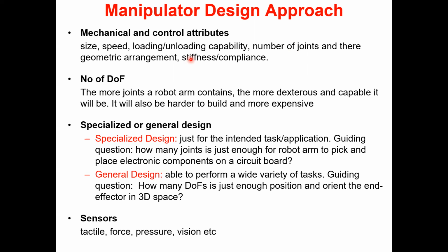One way to reduce the contact force is to deviate from the trajectory. Okay, you have a desired trajectory, and when you try to go through that trajectory, there is an undue, unexpected force, and to reduce that force, you deviate from the trajectory. So it is a trade-off between compliance and stiffness. Okay. So whether you want to have that in your design, you have to decide consciously. Okay.